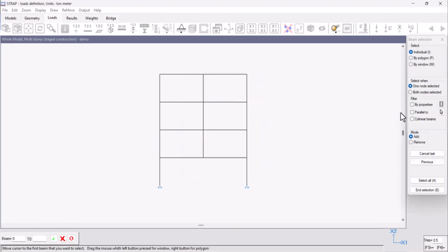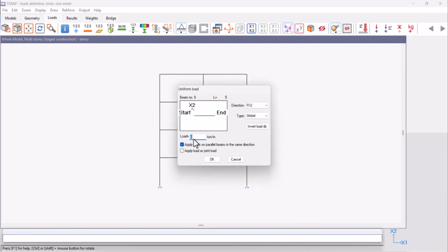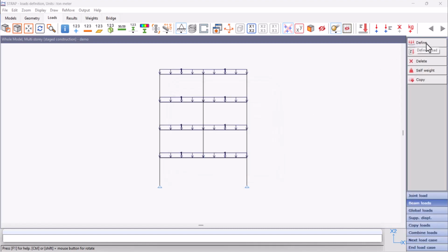In many cases, structural analysis involves applying loads to the entire model at once, similar to the load case depicted on the screen. This method can be inaccurate for certain loads, leading to significant discrepancies between the model-based results and the actual structural response. Essentially, as the number of construction stages increases within a structure, so do the discrepancies.